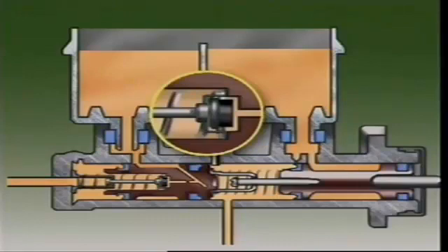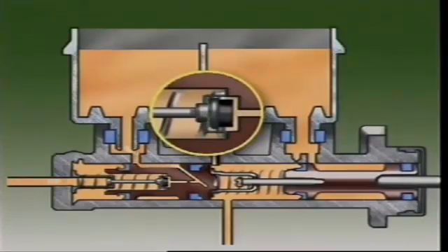When the piston has returned to the rest position, the seal is pulled off its seat by the action of the link and spring. This lets fluid still returning from the wheel units displace fluid back to the reservoir.